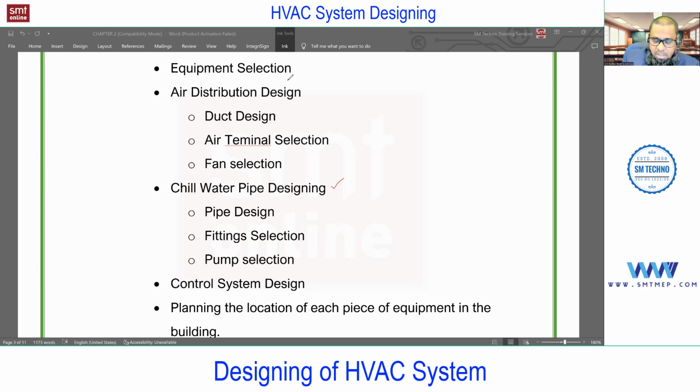And water system design is for chillers only, not for DX system. And if you talk about the VRF, then separate VRF pipe sizing. That also we'll discuss. You can consider this ductable split or split system as a DX system. Even VRF is also a DX system, direct expansion. And the chill water, air cooled and water cooled, comes under chill water system.